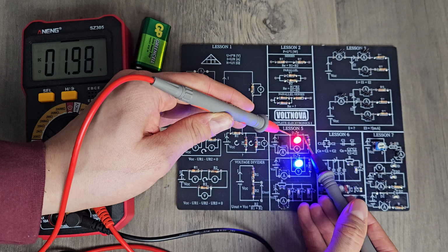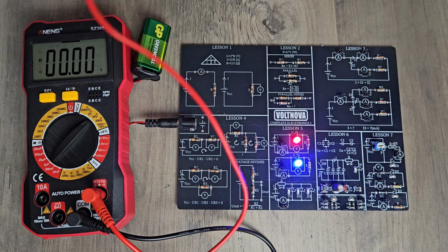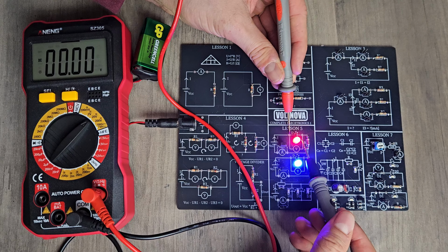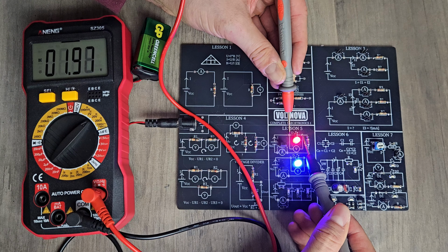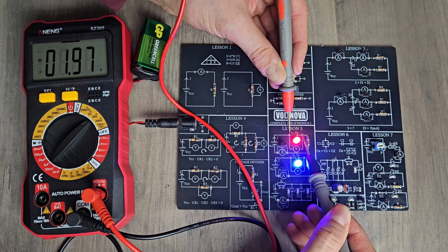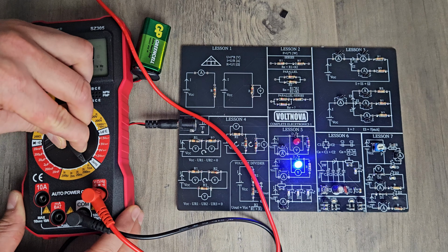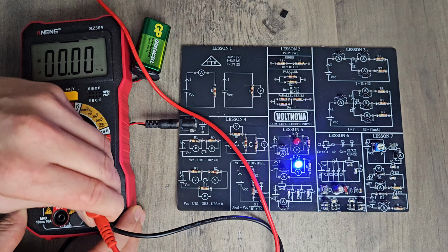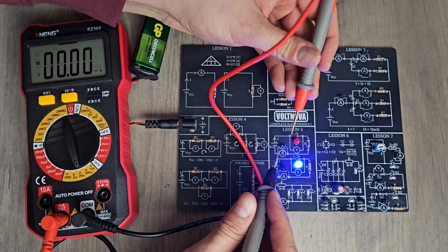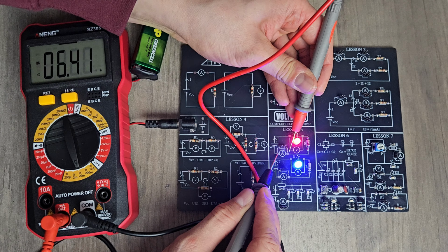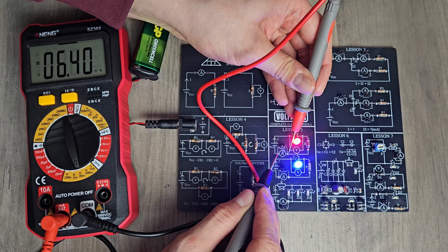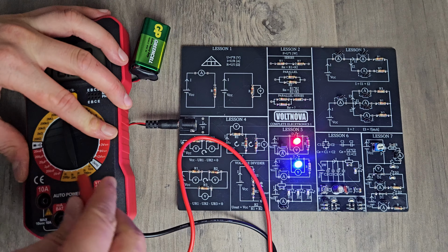You must remember that LEDs have ranges, so if the values differ somewhat, there's no need to worry. Let's first check the voltage across the red LED, and it's even close to what we calculated. So if the voltage is similar, the current will be similar too. We have changed the measurement on the multimeter and check the current. And as we expected, the current is also similar. That's a good sign. Here you can also clearly see that current flows through the meter because when we measure, the circuit starts working. Now the voltage across the blue LED.